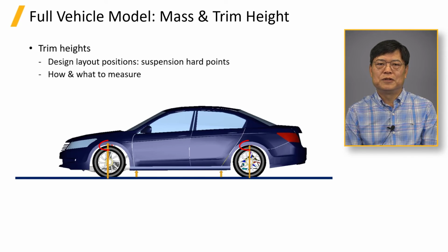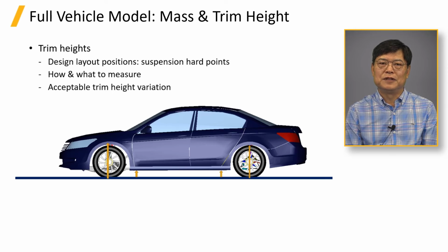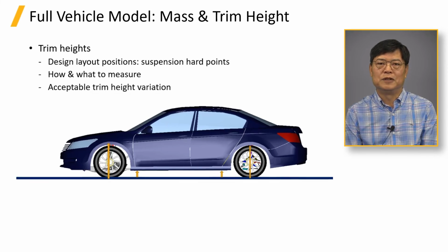The wheel housing opening is a good point to measure, which is easily accessible. The body rocker location, jack installation location so to speak, is also good for trim height measurement. The trim heights from the wheel housing opening and a body rocker have the effect of tire radius change. It would give substantially different numbers on hot summer afternoon and in chilly early morning.